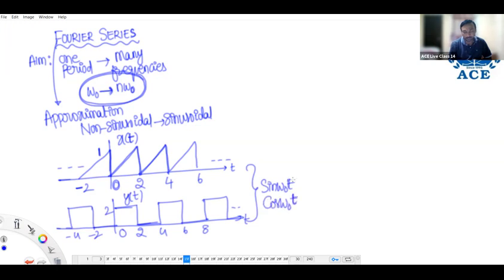In network theory, a sinusoidal input to an LTI system, a linear system, will reproduce a sinusoidal output. For an RC or RLC circuit, if you apply an AC source, the steady state response is a magnitude scaled and phase added version of the original signal. That is possible only with sinusoids, not with non-sinusoids.